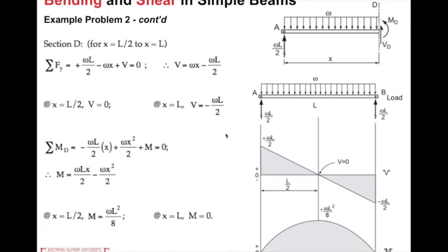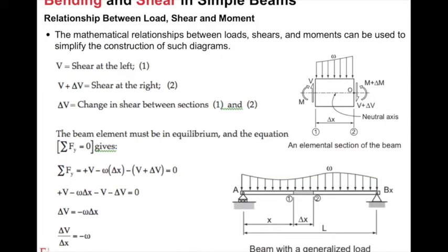Okay, so that's some pattern you can memorize to help you just draw the minimum section card to complete the entire piece of the V diagram and the M diagram.